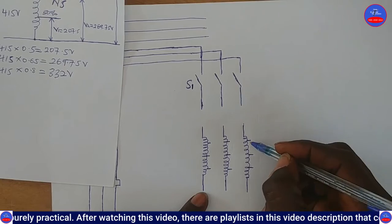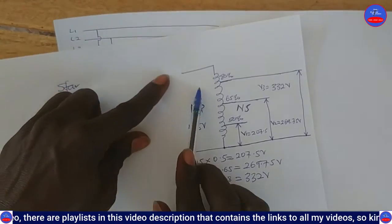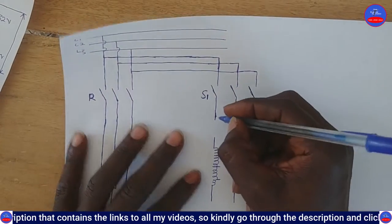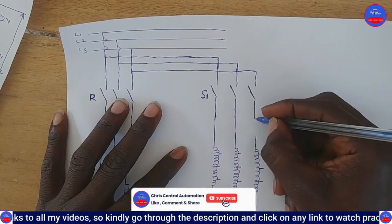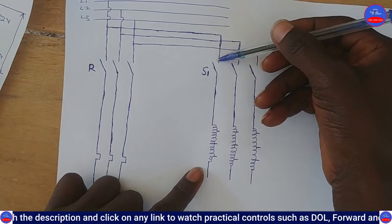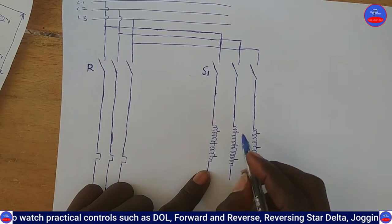And then the main voltage will be applied to the primary windings. As I told you, here the main voltage, the 415, is applied to the primary windings. So we are going to join this one like this. When this contactor picks up, we have applied the main voltages onto the primary windings. And then the secondary windings will be these ones.